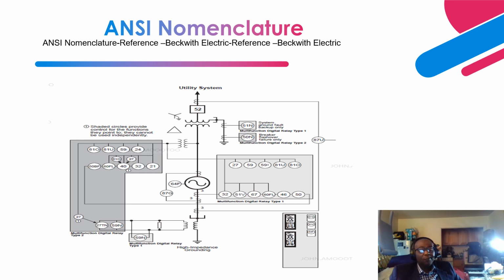This is the single phase distribution transformer that is utilized to achieve the high impedance grounding. Basically, what it does is it limits the ground fault current to about 5 to 20 amps, to prevent damage to the stator winding and the stator core.